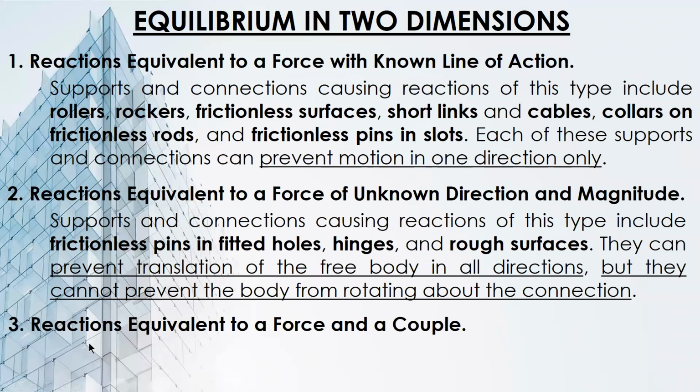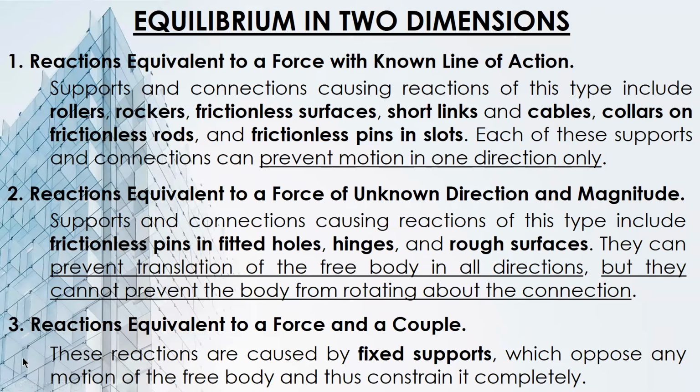Now, number 3, reactions equivalent to a force and a couple. These reactions are caused by fixed supports, which oppose any motion of the free body and thus constrain it completely. Oppose any motion, translation, and rotation. So, it cannot move along X, cannot move along Y, and it also cannot rotate.